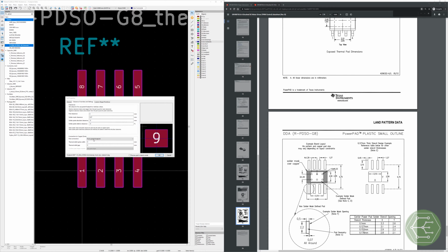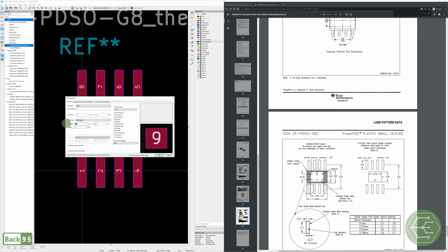Okay, with the paste clearance set to 0, I think we're all set, though it does want solder mask. Yeah, that should be fine. Solder mask. Oh, wait, they want a solder mask defined pad there. I totally goofed that. Okay, so they want 2.95 and a 4.9.